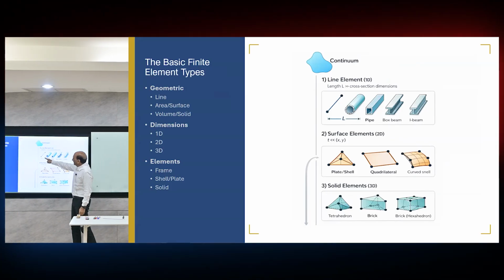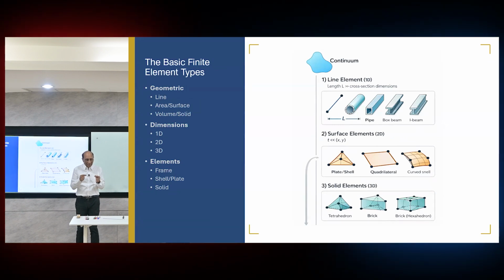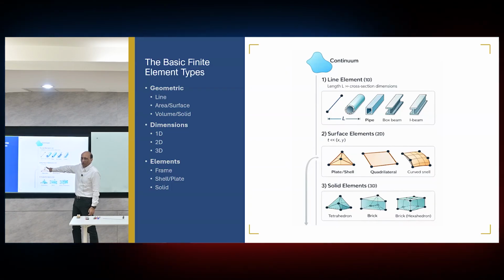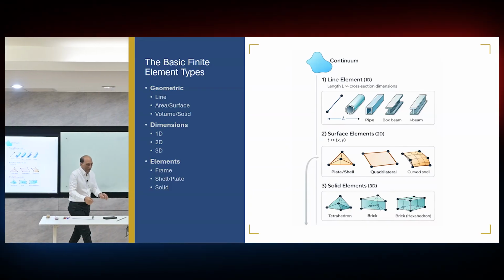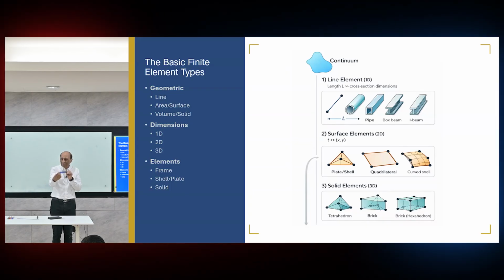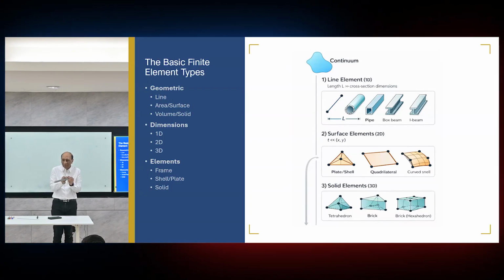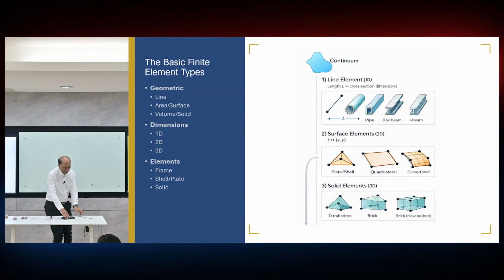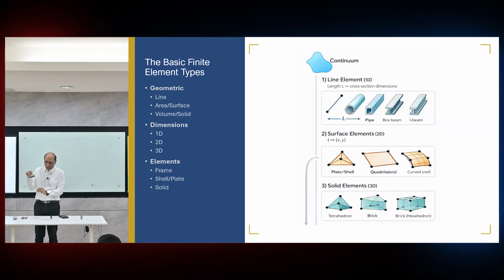One is that if the length is very long and the dimensions are small, then we take the length as the primary modeling parameter. In this one, we take two directions, x and y, as the modeling, and t is a property. So here length is modeled, and the cross-section becomes a property. That means the line element doesn't care whether it is a big one or a thin one, it's always the frame. So that's why I say, if the beam is very large, is it justified to create a beam, and very short? We come to the problem of the deep beam that we studied. Same thing here. So for us, this one and this one, both are shell. But if this one becomes like this one, is it shell or should it be solid now because it's too thick, right?